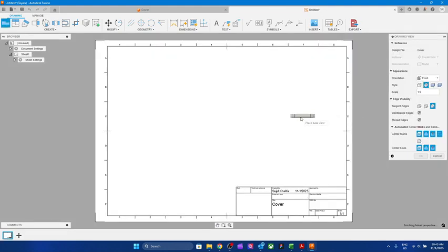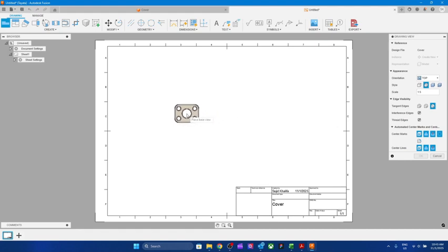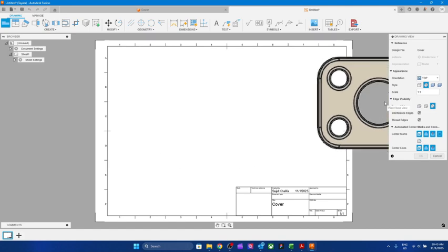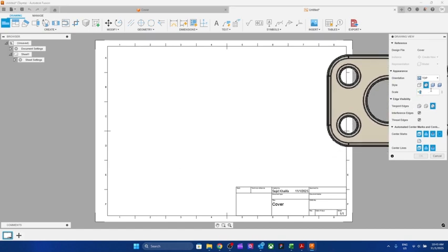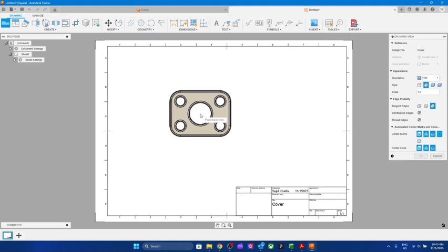Here we go. Now you're ready, and it's giving me the front view. I don't want front view, I need the top view. So that's my top view, okay? But it's too small. So I want to simply say it's going to be 1, 1, for example. That's too big. 1, 2, that's reasonable size, okay? 1, 2.